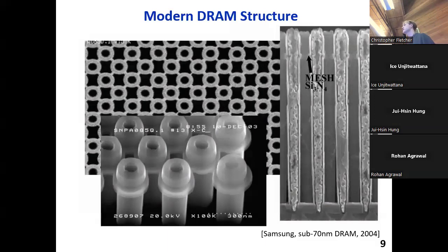The ones on the previous slide were these stubby things. On this slide, these long tubes are the capacitors. They look much more elongated and stripped down. And this is what DRAM cells look like today. This technology is called deep trench capacitors, and they go by various names, but that's one of them that you may recognize.